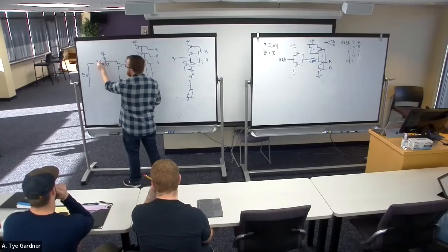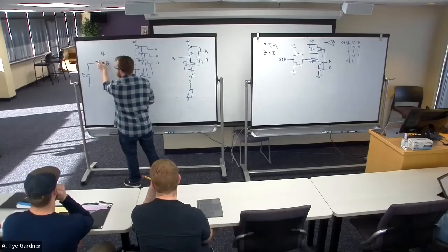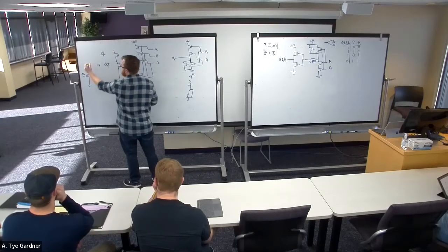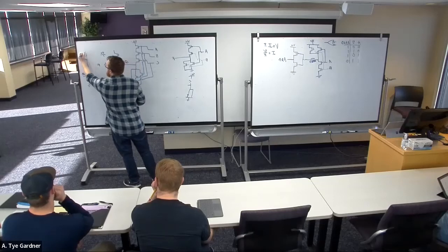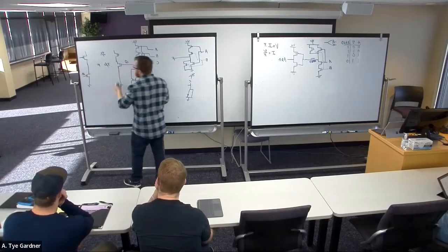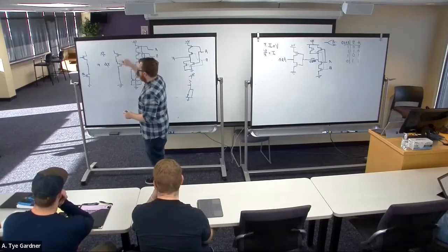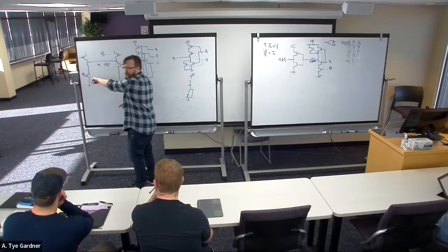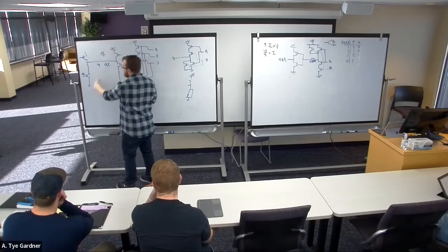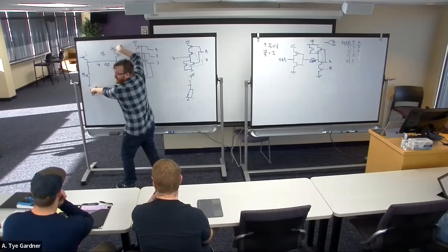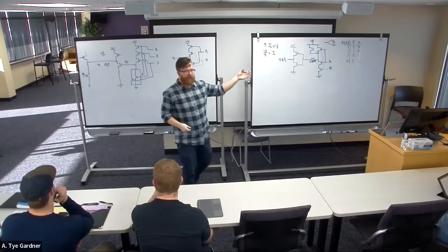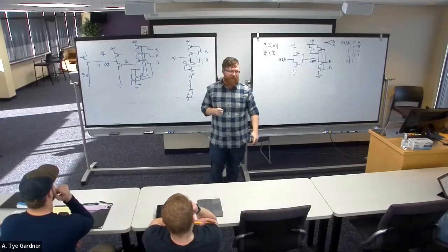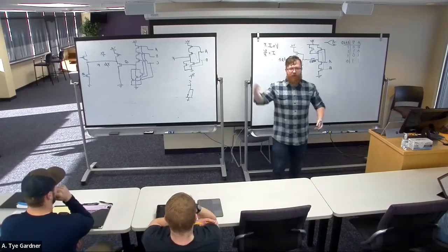Whereas if instead of this, each side had PMOS devices and tried to talk, and this one says 1, and this one says 0, then the current from VCC to ground, there's no resistor in between, there's no current limiting resistor, the current goes to infinity, and you just broke both devices. Right, not good. So that's where the open drain comes in.